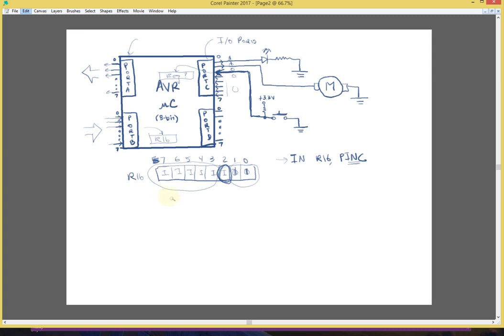So for example, I can have a mask where I set this to 0, 0, 1, 0, 0, 0, 0, 0, and when I do the bitwise AND operation between these two, then all of the bits are going to be 0, and this is going to give me the bit value of whatever this one is.